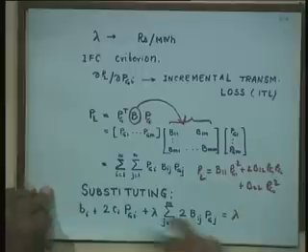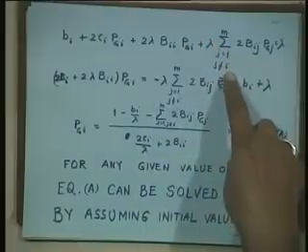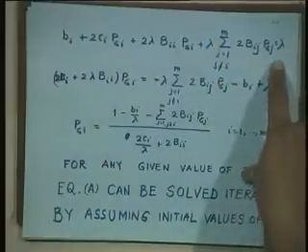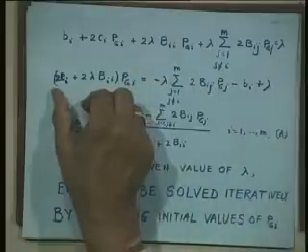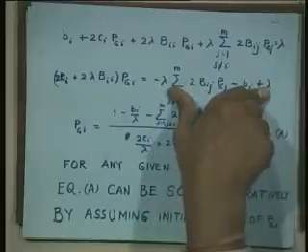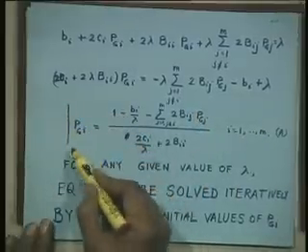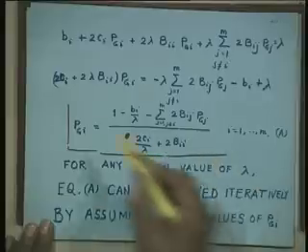Once you get this equation, since I am interested in finding the value of PGi, I separate out PGi from here. So j not equal to i, the rest of the terms are the same. Then I collect all the coefficients of PGi, which I normally do in deriving anything. The rest of them are on the right hand side. So PGi becomes this, and this is CTM. CTM is commit to memory.